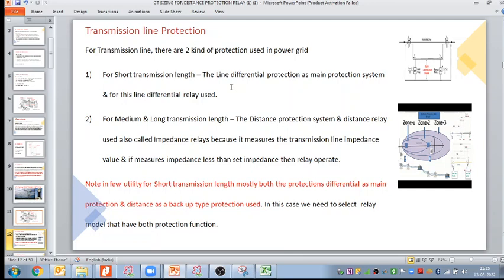Yeah, the main reason we go for differential protection is, suppose for example, a short line. What we refer to as a short line is a distance of less than 5 kilometers, for example. So what will happen is, as we have already seen, we have errors in CT. In case of transmission line protection, distance protection is basically not a unit protection.